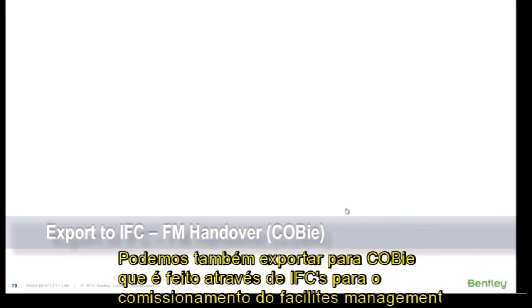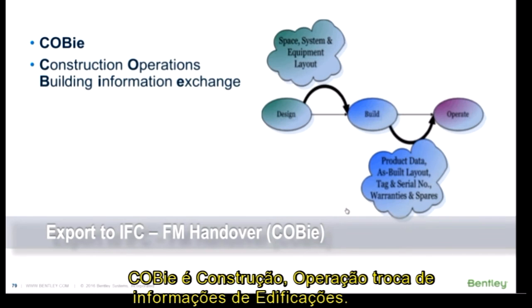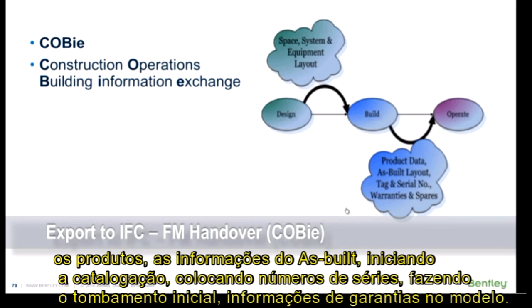We also can export to COBie, which is going through IFCs for facilities management handover if you're going to some other FM systems, enterprise solutions. So COBie is the Construction Operations Building information exchange. If you don't know what that is, that's when you're going from design, build into operations. When you're going from build into operations, that's where you want to be taking all that product data, the as-built information, and start pushing tag data, serial numbers, warranties, information into the model.